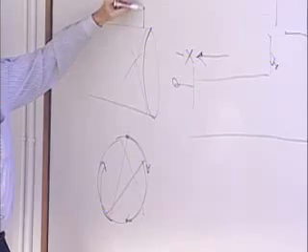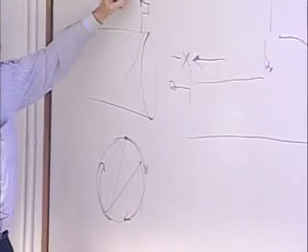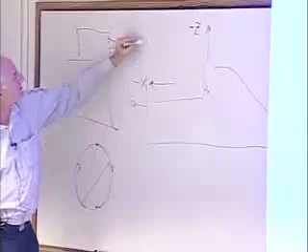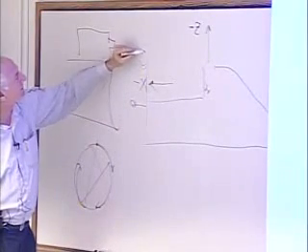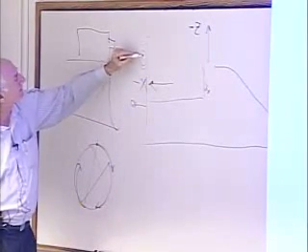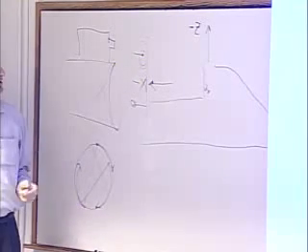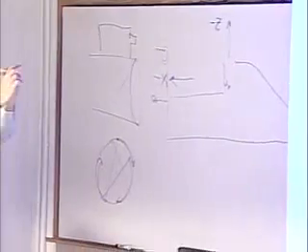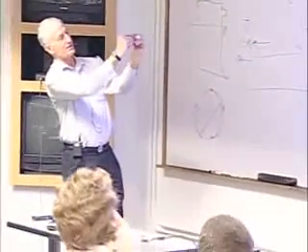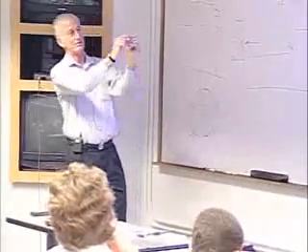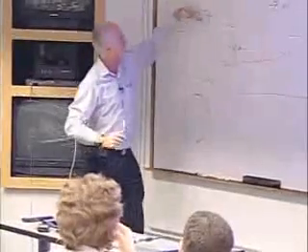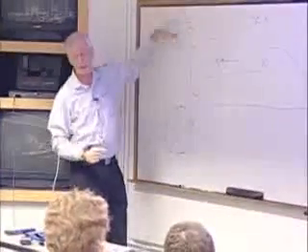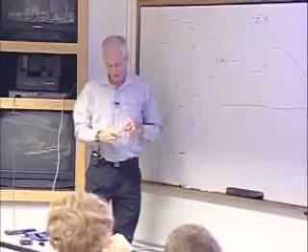There's a camera up here, and above the grapple fixture there's a bullseye with a little stick on it, so that if you're off to the side a little bit, you can see by the angle on the stick both how you are in translation and in the attitude of the end effector.